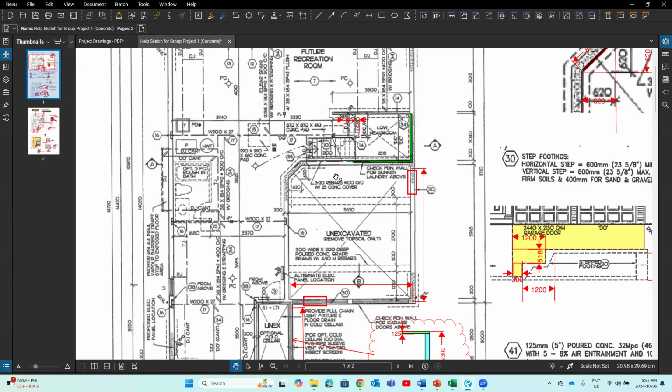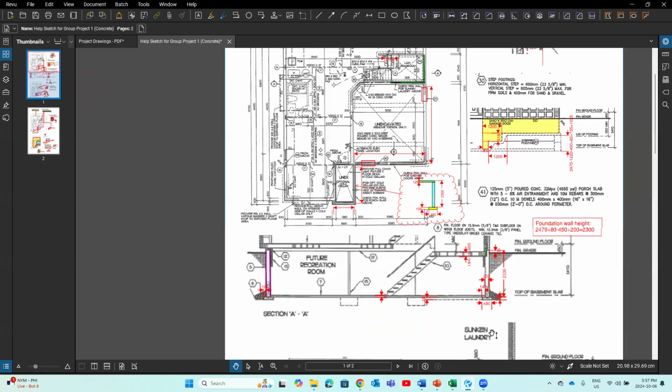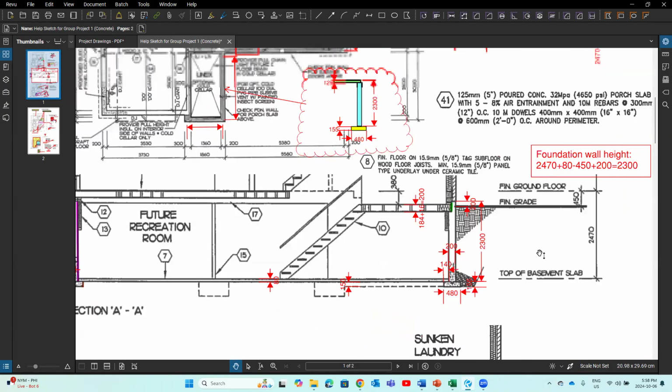Formwork to foundation wall, like I said, this foundation wall goes around for the basement. Once that's done, we can find the depth of that, right? We take the perimeter center line length, multiply by height. So if I draw that, we do the analysis, right? You see, we have this dimension here, right? We take this dimension, we subtract this dimension, we need to add 200.